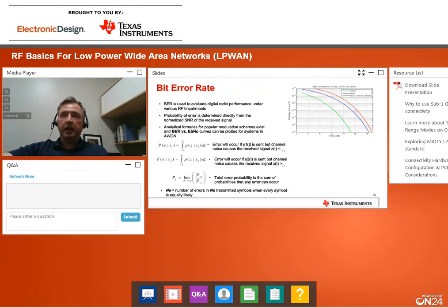So yes, there is. There is a theoretical limit of what the SNR can be for any kind of modulation, and that is called the Shannon Limit. This limit defines the required signal-to-noise ratio to decode 1 bit at some certain occupied bandwidth, so say 1 bit per hertz. This defines a lower limit for what can be achieved with any kind of modulation. There's nothing that can get better than that.